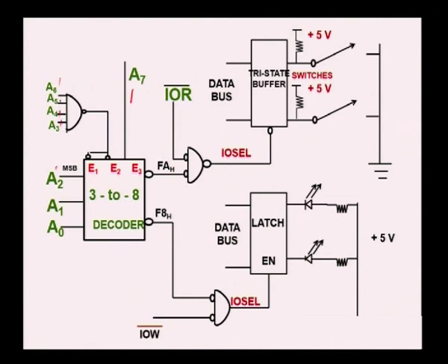After selecting FA, we have to give 1 1 1 for the upper address lines. Here we are selecting 0 1 0, so the address bits are 1 1 1 1, 1 0 1 0. This is F, this is A. So here we are giving FAH, and by FAH we are reading the data. The read bar signal is activated, then it will select. Whatever switches are closed or open, based on that the ones and zeros are read and transferred to the processor via the data lines.